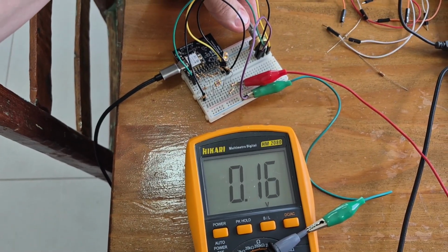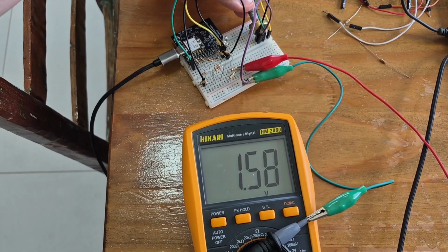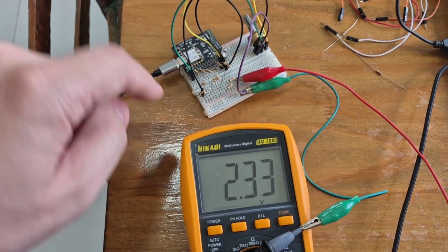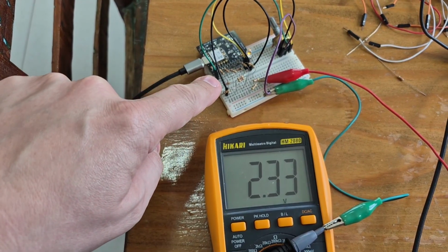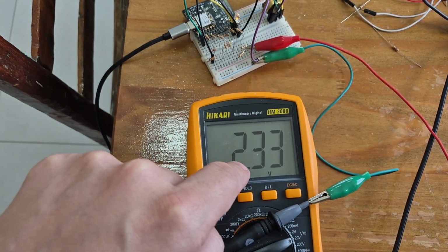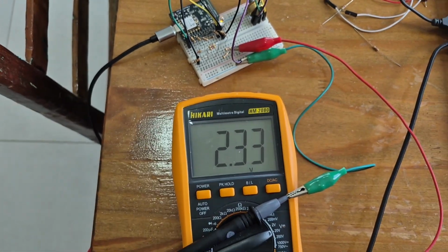So effectively, turning the potentiometer alters the digital value applied to the resistors, and then alters the analog value present at the output. So guys, as you saw, it is possible to use a couple of resistors. In my case, for a 6 bit analog output, I use 12 resistors and one microcontroller.